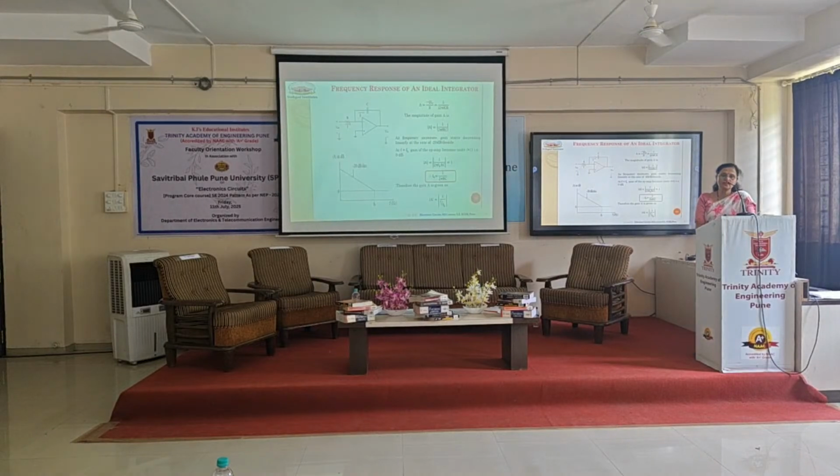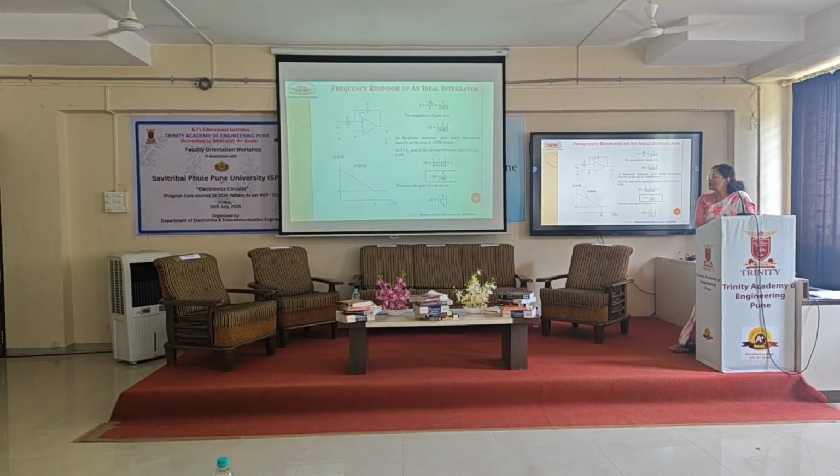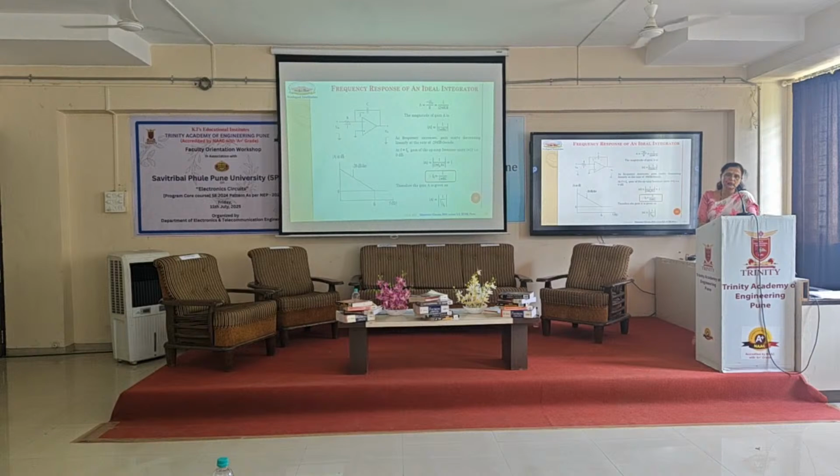It has a problem in the low frequency range because when f equals 0, the capacitor acts as an open circuit and that makes the circuit unstable, meaning it enters into the open loop gain. This is the main limitation of this frequency response. And one more point we have to mention is the unity gain, and that unity gain depends upon the value of RC.